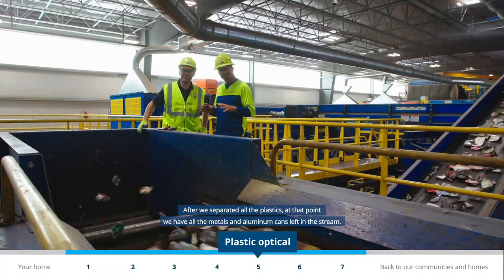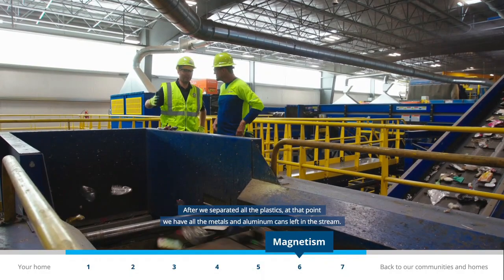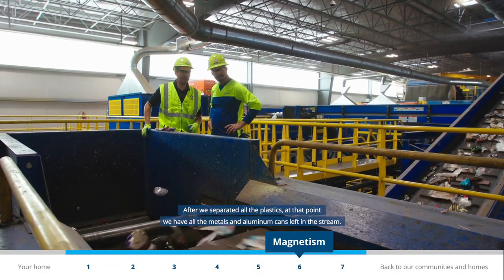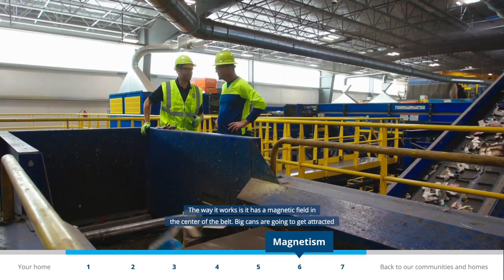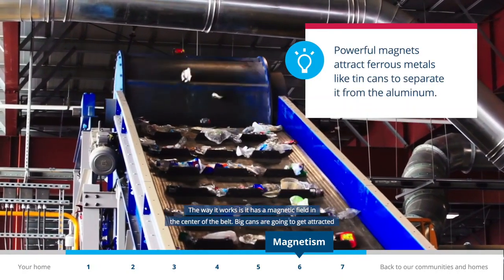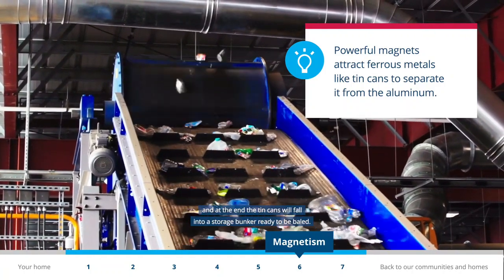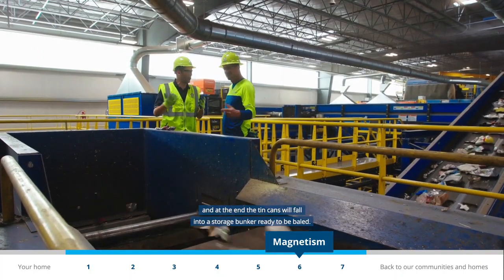Powerful magnets are strategically placed to separate metals from plastic and divert them to their correct destination. After we separated all the plastics, at that point we have all the metals and aluminum cans left on the stream. So first of all that material will go through our magnet belt. The way it works, it has a magnetic field in the center of the belt. The tin cans are going to get attracted, and at the end, the tin cans will fall into a bunker. The storage bunker is ready to be baled.